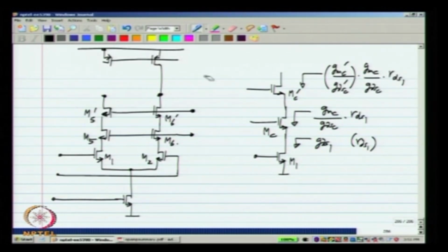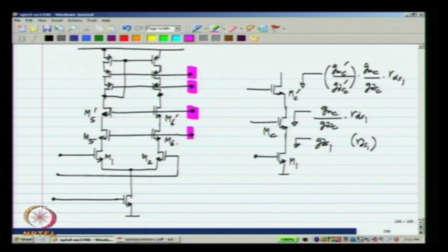So, I should have a current mirror which is also triple cascoded. So, you need to establish the bias voltages at all these points, so that all transistors remain in saturation, and of course, a similar thing can be done with the folded cascode as well.